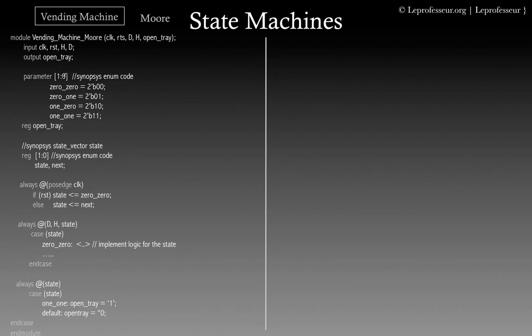Now if you specify here say 3 down to 0, and you assign these states as 0 0 0 1 and specify those parameters, it will make it a one hot encoded state. So this example discusses the binary encoding, but that's the only difference here, how you specify the